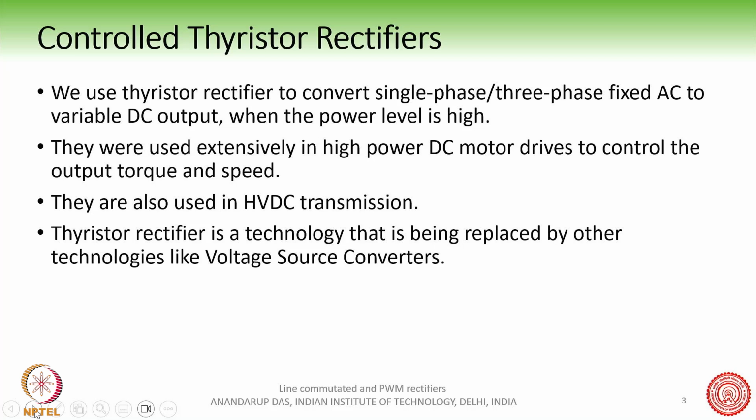But nowadays DC motors have been replaced by induction motors or PMSM, so thyristor rectifiers are no longer used there. They are still used in high voltage DC transmission, but these rectifiers are slowly being replaced by voltage source converters. In LCC based, line commutated HVDC transmission, we are seeing a transition from LCC to VSC based HVDC transmission.